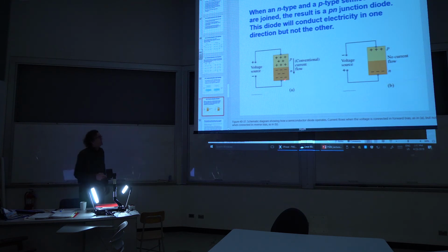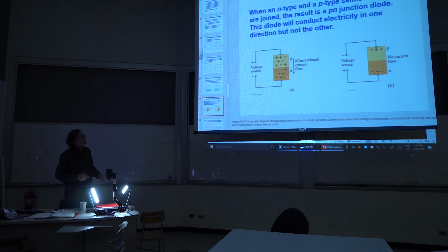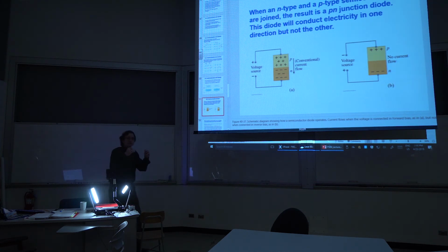So notice that we are drawing a picture of p-type semiconductors with an abundance of holes due to the doping of gallium atoms replacing silicon atoms. And we're describing the n-type semiconductor with a bunch of minus signs indicating the abundance of extra electrons given by the arsenic.